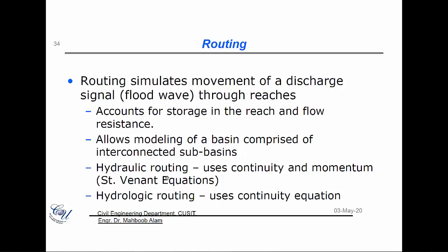As we said earlier, there are two methods. Hydrologic routing only uses the continuity equation plus another storage equation, the storage elevation equation, which I'll be explaining in a couple of slides. And then there is hydraulic routing, which in addition to continuity also uses the momentum equation.